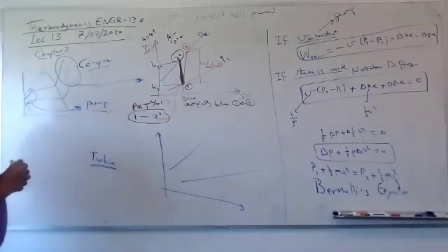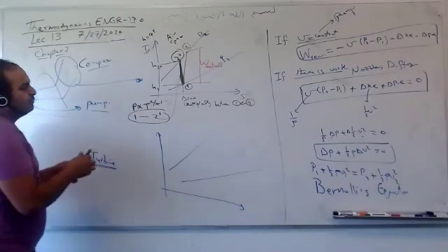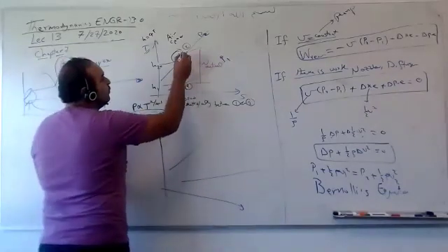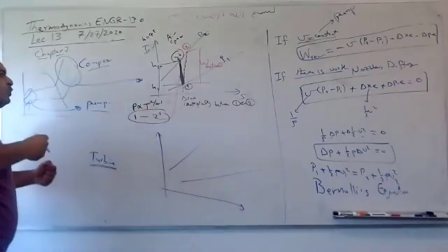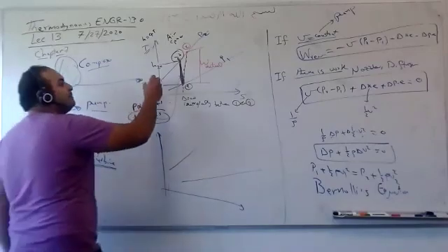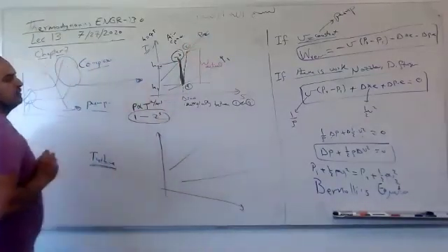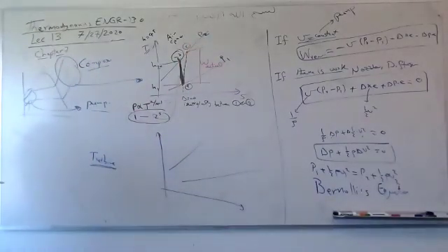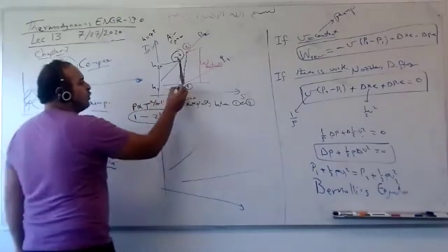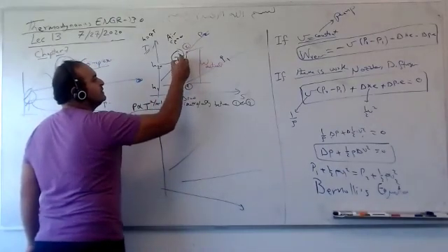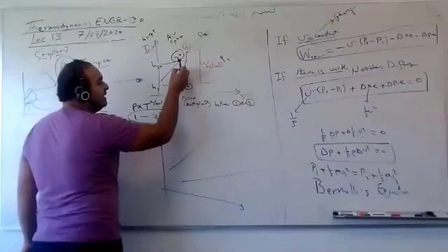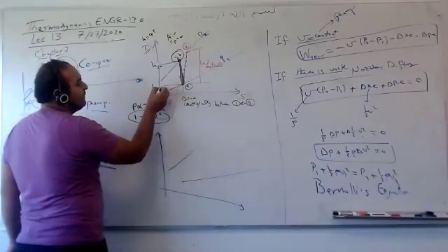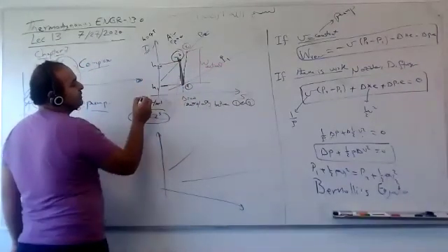But in reality, we have these losses. We pay more work to go to the same pressure line. I wish to go from 1 atmosphere to 10 atmospheres. If I go vertically, I pay this amount of energy, h2S minus h1.